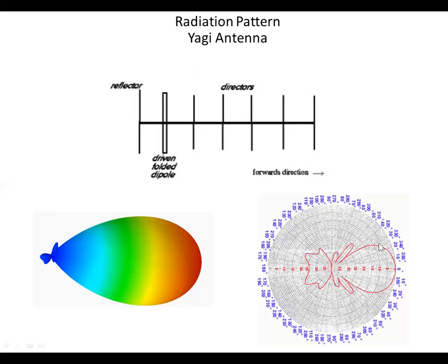Say if you're pointed towards Northern Europe, this would probably be up at say 45 degrees. Well, you'll still have lobe transmitting and receiving off the back end, say down into Texas and Arizona. It just won't be as strong as what you're sending and receiving on this main lobe. So that's how a directional radiation pattern looks.